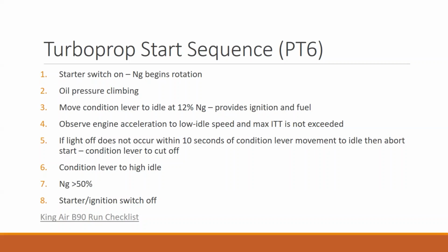We're starting to move the gas generator. What's the gas generator made up of? What makes up the gas generator? So you've got a compressor and a turbine, the turbine that drives the compressor. So you're going to get airflow through the engine. And it's that airflow through the engine hitting the free power turbine that's going to start rotating it. In fact, if you know you have a free power turbine, you can hold the prop still while the starter is engaged. You'll feel a little bit, but not much.